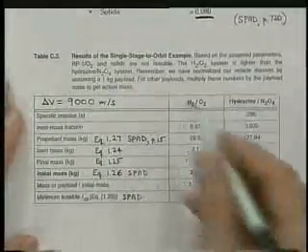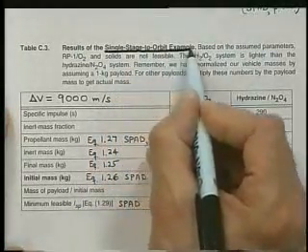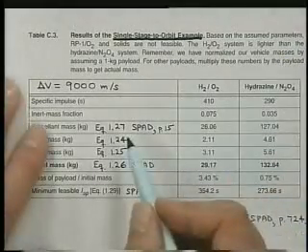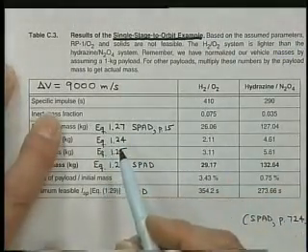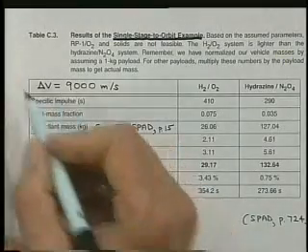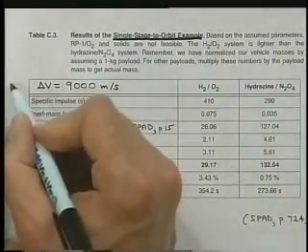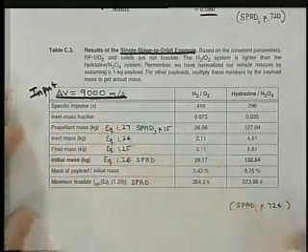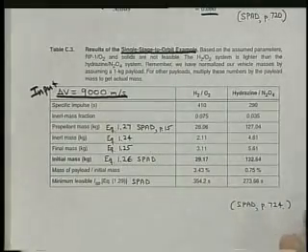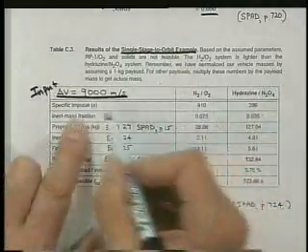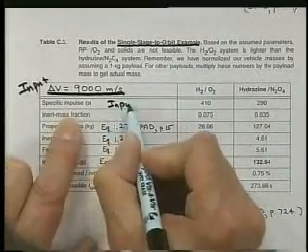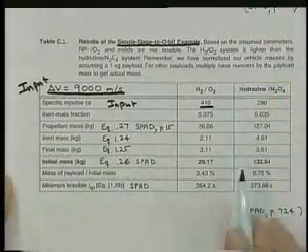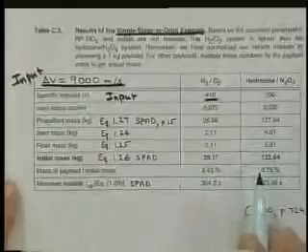So let's compute some single stage to orbit examples, or go over the computations done in the SPAD book, although I highly recommend doing the computations to understand the details here. Let me label for you what the inputs are. You need the delta V to even get started, right? And you put that into the rocket equation. Then you need an input of the specific impulse. So here's the hydrogen LOX case. Let's look at this column and see what the numbers are telling us.